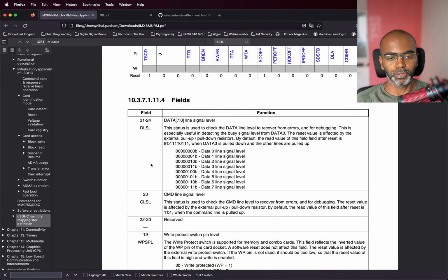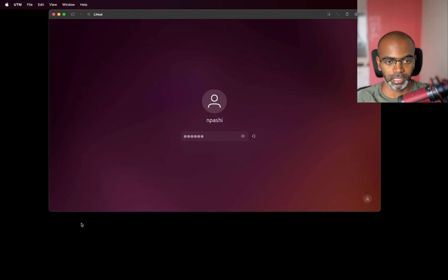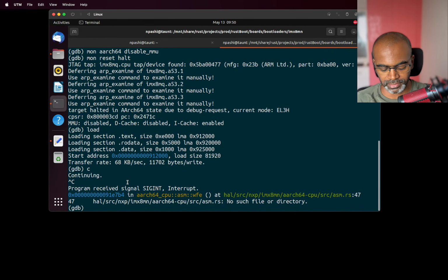Cool. So now that you understand the context, and now that we've got this particular driver working, let me explain these commands a little more. Let me go back to our debugger, and let me actually examine the memory addresses to see what's actually happening over here. So you could go ahead and inspect memory of the peripheral block itself, all their registers. You can see what the values of those registers are through GDB with these commands.